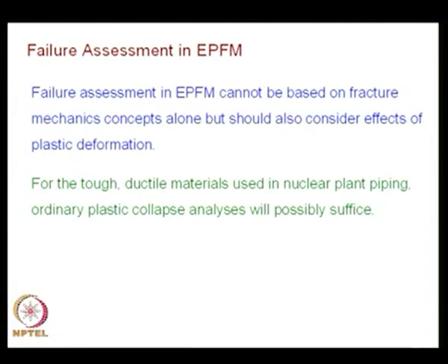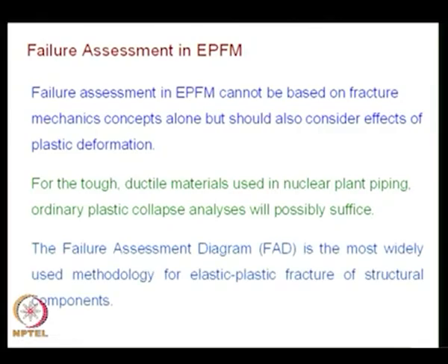So, if you look at the nuclear plant piping, which is made of tough ductile materials, ordinary plastic collapse analysis will possibly suffice. And the failure assessment diagram, abbreviated as FAD, is the most widely used methodology for elastic plastic fracture of structural components.